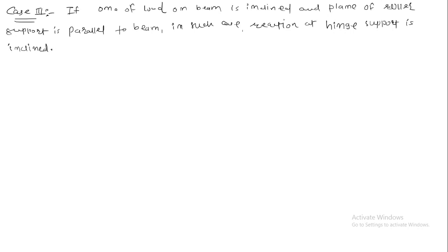Case 3. What is the case 3? If one of the loads on the beam is inclined and plane of roller support is parallel to beam, in such a case the reaction at hinge support is inclined.